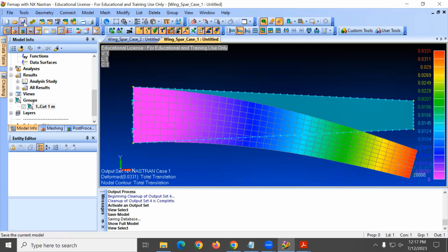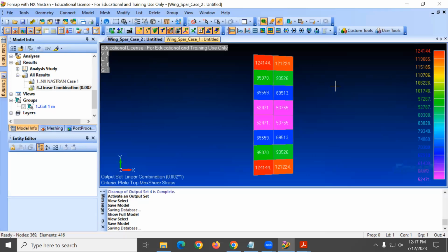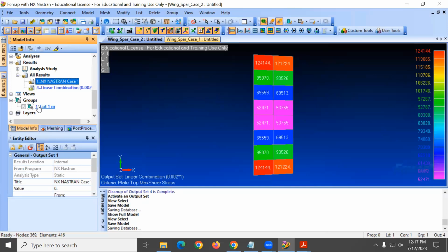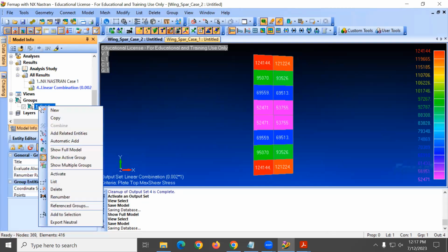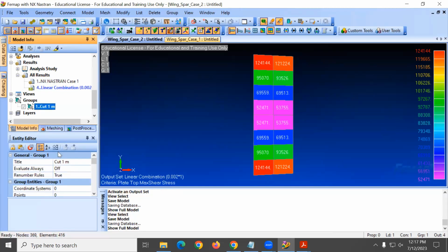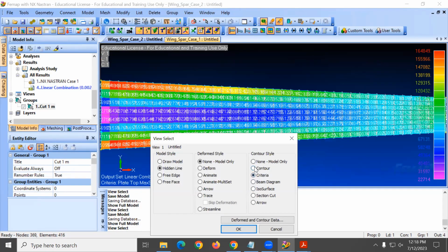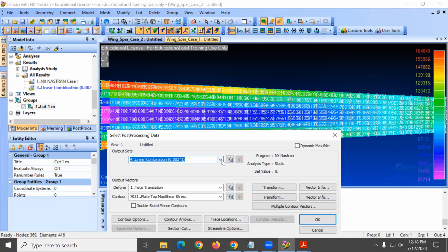All right. Now, if we go to case 2, what did we do in case 2? If you remember, when we calculated the I, we took into consideration the thickness of the panels, no? So let's see. Probably the panels are too thin. Here I multiplied everything by 0.002, so it's not going to work. It should give me a nightmare, but maybe we can remultiply. If we do F5, contour, deform, it multiplies everything by 0.2. Oh, maybe not. So hold on.